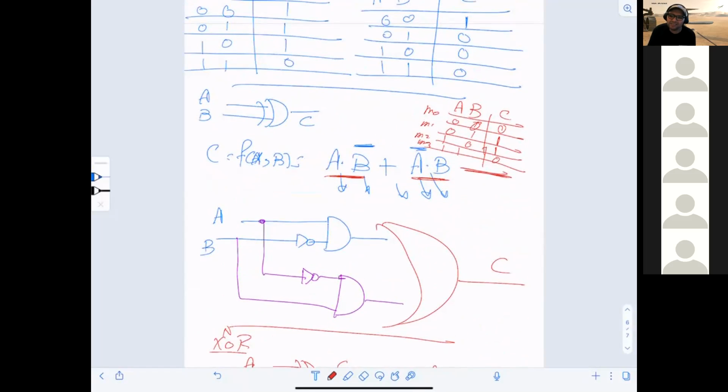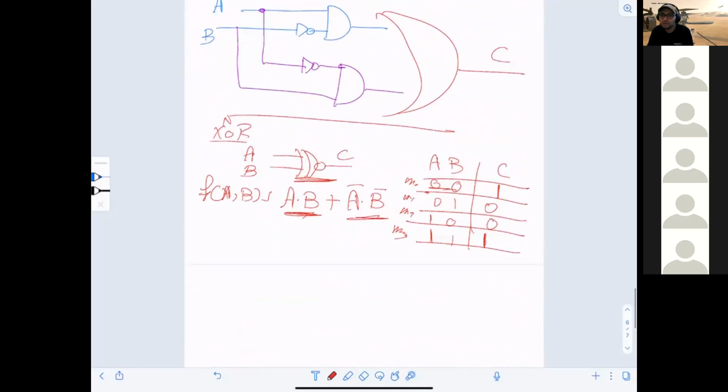So you can actually learn that XOR is looking for the odd number of ones, right? So for 0 and 1, it's just one 1, odd, so 1. 1 and 0, 1. When it's 1, 1, that's even, right? So 0. And when it's 0, 0, that means we consider in theory that it's even, so that's why it's 0. For XNOR, it's the vice versa. With 0, 0, that's even, so it's gonna be 1. When it's 1, 1, it's even, so it's gonna be 1. Those with odd are 0.